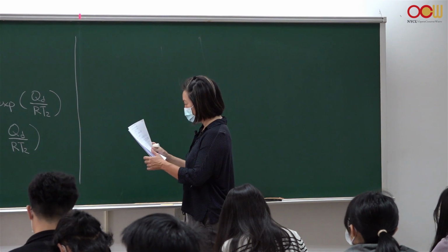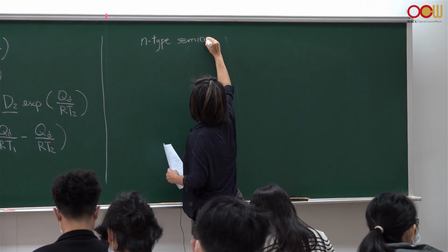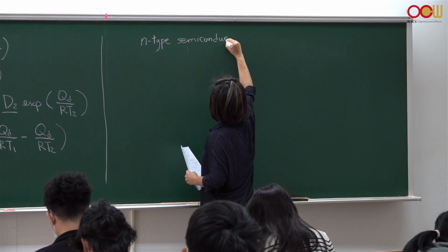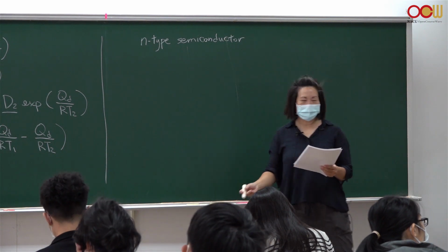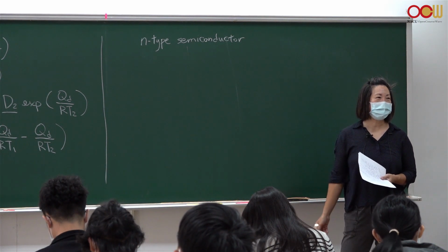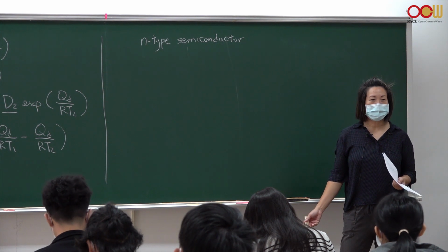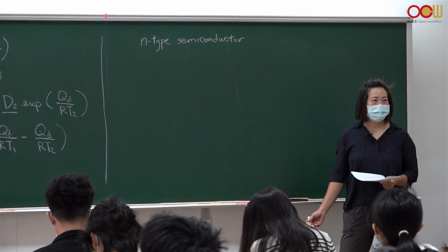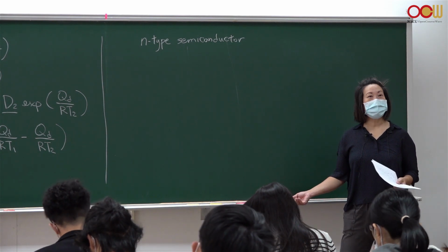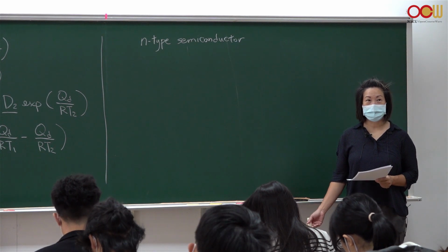And you want to make an N-type semiconductor. And we will talk about in this class later how to do that, what that means, why you do the doping that you do. But basically, to make an N-type semiconductor, you start with pure silicon, and you add impurities. You can add impurities in several different ways, but one of the ways that people still use is by diffusion.